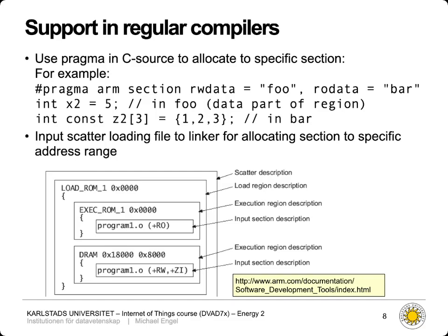And now we can use something we call a linker script. A linker script is responsible for telling the, well, compiler, or to be precise, the linker, which produces the final binary. And the linker script actually instructs the linker which sections of the code go into which addresses.